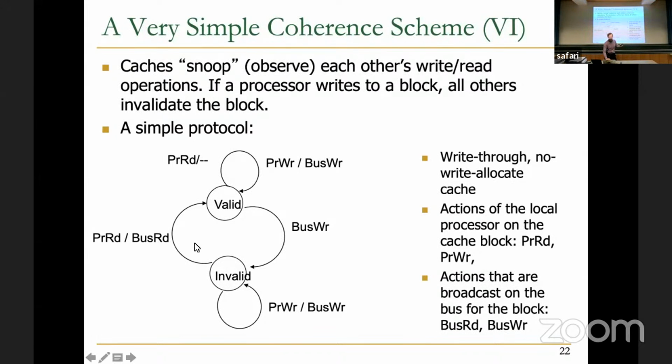Now, this bus read request actually is meaningless in this particular protocol. If you study the protocol, you will figure it out, because whenever you receive a bus read request, you don't do anything. You can see that there's no state transition that happens when you receive a bus read request because of the way the protocol is designed.